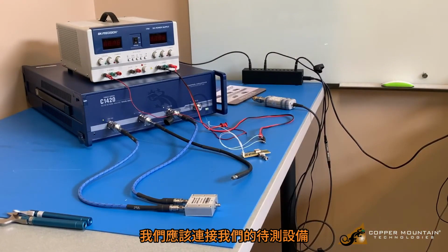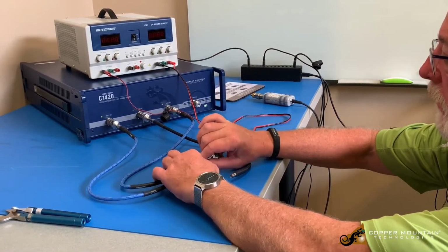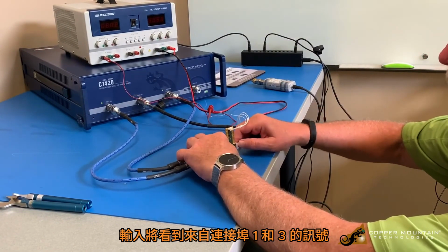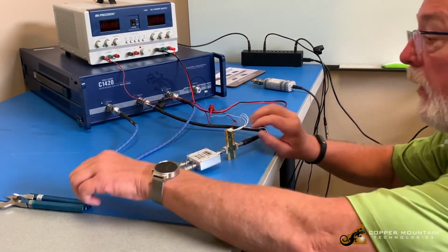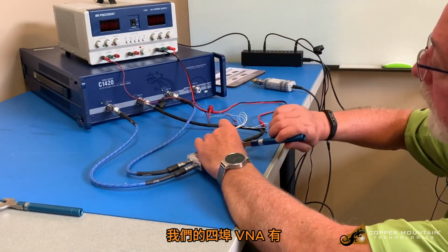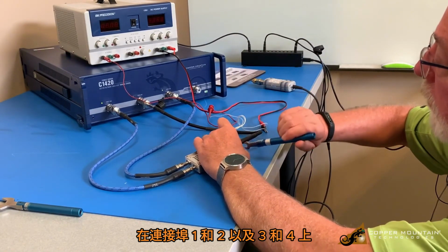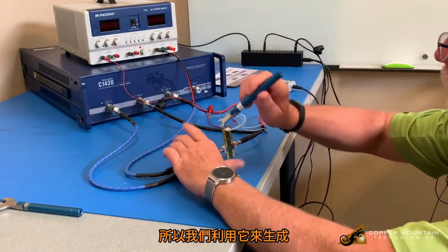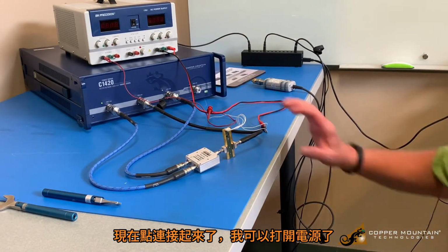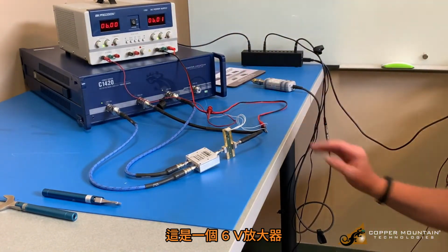We should attach our device under test. So let's do that. And we'll do that with the power turned off. The input will see the signals from ports 1 and 3. I should mention that our 4-port VNAs have the capability of generating separate signals on ports 1 and 2 and 3 and 4. So we're taking advantage of that to generate the second tone from port 3. So now the DUT's connected and I can turn on the power. This is a 6-volt amplifier.